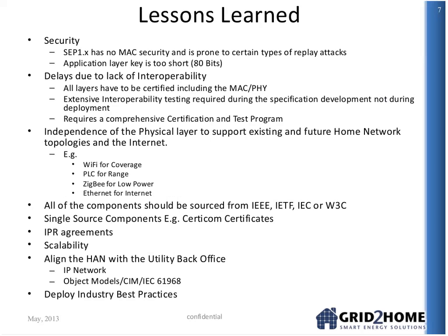On the security layer, SEP1 had no MAC security, and it's actually prone to certain types of replay attacks. I won't go into what the security hole is because that would encourage people to go and hack it, but it does have no MAC layer security. And the application layer key used is a bit short. It's 80 bits long, and today the recommendation from NIST, for instance, is at least 128 bits. 80 bits is a very short key length.